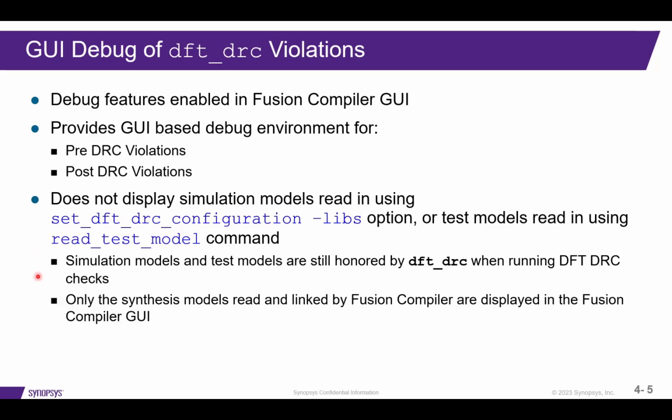Now, the simulation models or test models are still being honored by the DFT DRC command when you run the test design rule check, but only the synthesis models read in and linked by Fusion Compiler are displayed in the Fusion Compiler GUI.